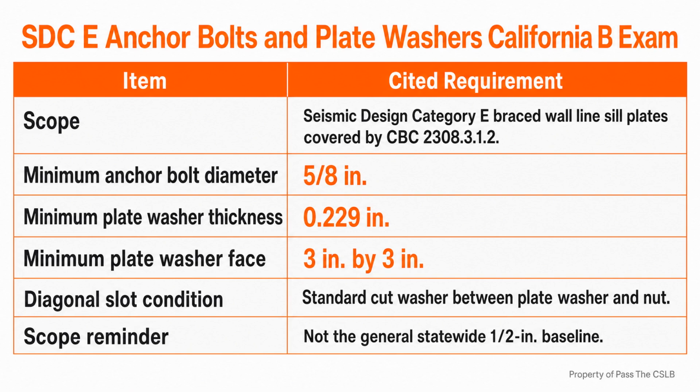A familiar manufacturer name on the box does not replace the approved schedule, and a different brand is not automatically forbidden merely because it is different. The controlling questions are whether the exact product and installation are approved for the project, whether the specified fasteners and capacities match the design, and whether any change has received formal approval. Visual similarity is not an engineering determination.